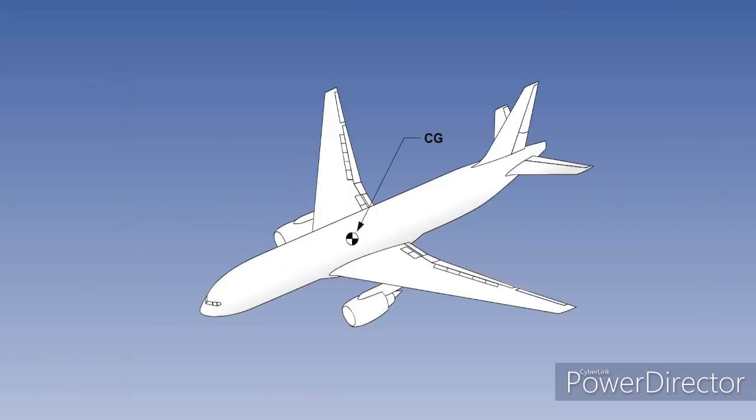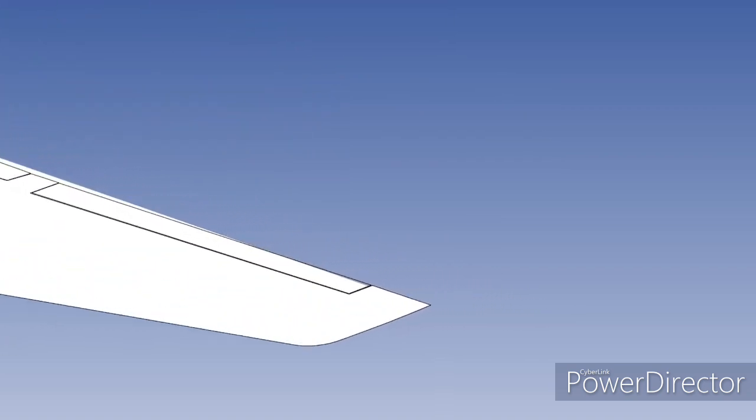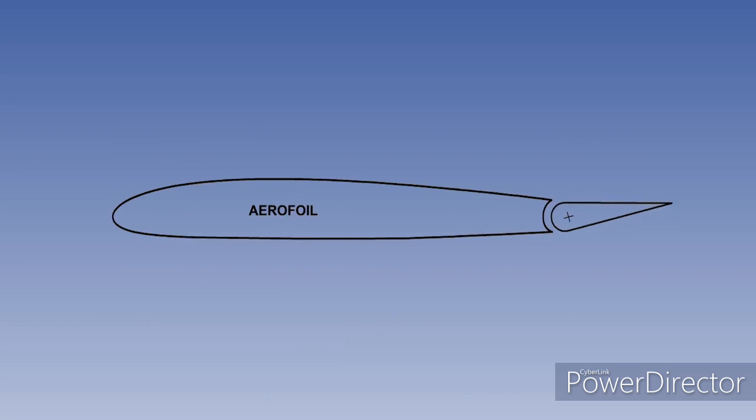An aircraft needs to be controllable about each of its three axes, which pass through the centre of gravity, or CG, which is conventionally portrayed by a circle with alternate black and white quarters. Basic controls will consist of flap-type sections incorporated into the trailing edges of the main flying surfaces, and positioned at the extremities furthest from the CG to give the greatest control movement.